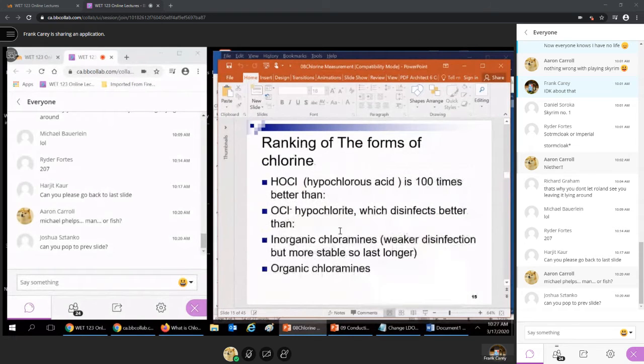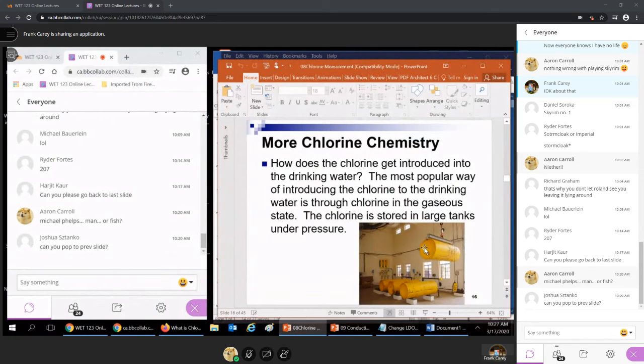So the downside with tonners, of course, is chlorine is a dangerous gas. If there is a leak, it is potentially dangerous. We do not like chlorine tanks in residential areas, and that's usually where wastewater treatment plants are. But it's cheap, relatively very inexpensive, especially compared to generating chlorine on-site, because you have to buy the salts and all this sort of stuff. It's very effective, very easy to use.